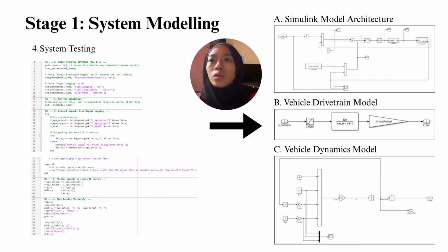And crucially, the model utilizes a feedback loop where the current velocity is squared and multiplied by an aerodynamic constant to dynamically update the drag force as speed increases. The resulting net force is multiplied by the inverse of the vehicle mass to derive acceleration, which is then passed through two integrator blocks in series to compute final vehicle velocity and position.